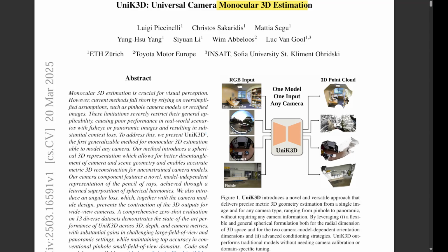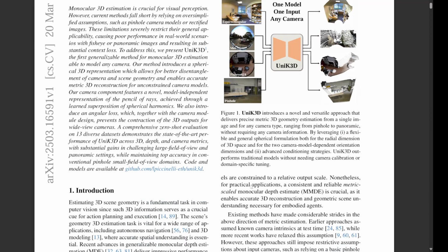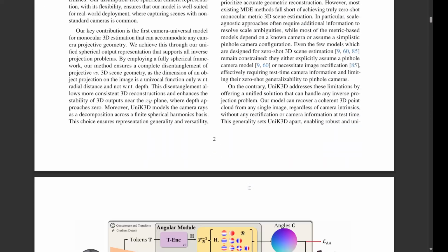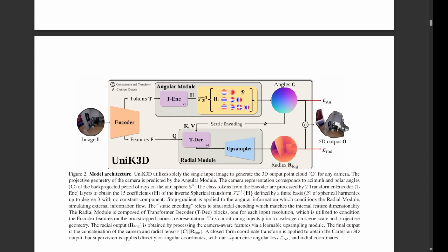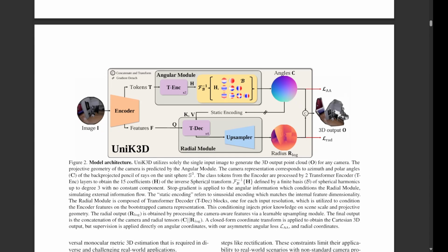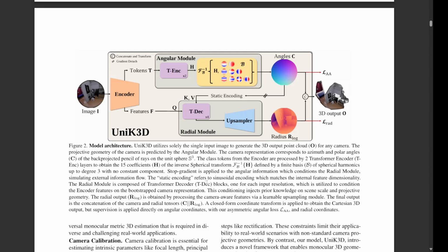All right, so let's start with that mathematical hurdle you mentioned. Why is predicting depth such a headache for wide-angle cameras, especially the really wide ones, over 180 degrees? Okay, picture a point way off to the side in a super wide image, like from a fisheye lens. If you're trying to measure its distance perpendicularly back to the camera's main viewing axis, tiny errors in figuring out its angle in the image can lead to huge swings in that calculated perpendicular distance. Ah, right. Like a small angular error gets amplified way out there. Exactly. The measurement becomes super unreliable.